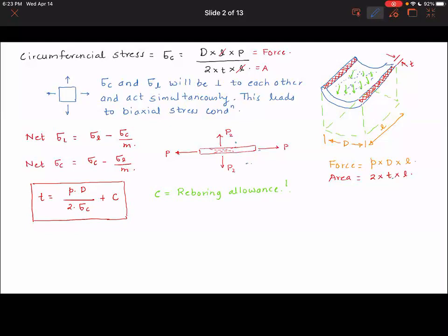After some time, you will notice the engine would lose efficiency, lose power, and start smoking. Or sometimes it could lead to lubrication failure and the piston cylinder assembly would just seize. In other words, the piston would jam inside the cylinder.